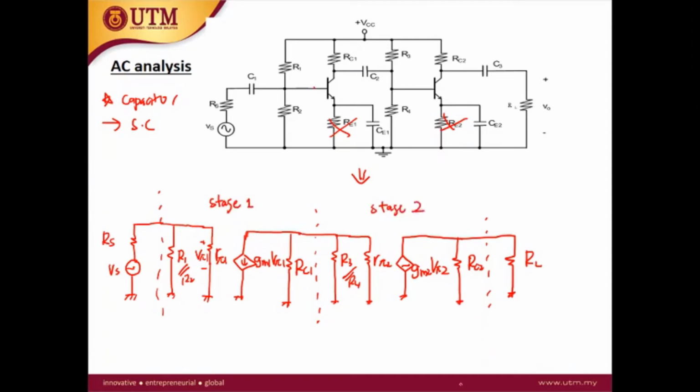Okay. So in the AC analysis, the component at the output side of stage 1 will combine with the input side of stage 2. So you can see that the stages cannot be analyzed separately. You need to consider the components from stage 2 when you analyze stage 1.